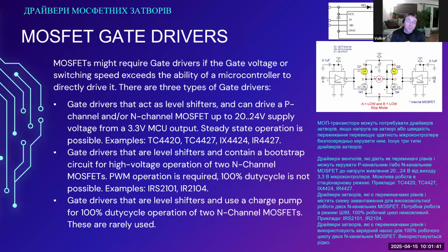The capacitor voltage is essentially riding on the high voltage, and it needs to do that in order to turn an N-channel MOSFET on. In an N-channel MOSFET, the gate voltage needs to be higher than the source voltage. So you need a voltage that is basically riding on top of your supply voltage. That is the difficulty with using an N-channel MOSFET for a high side switch.